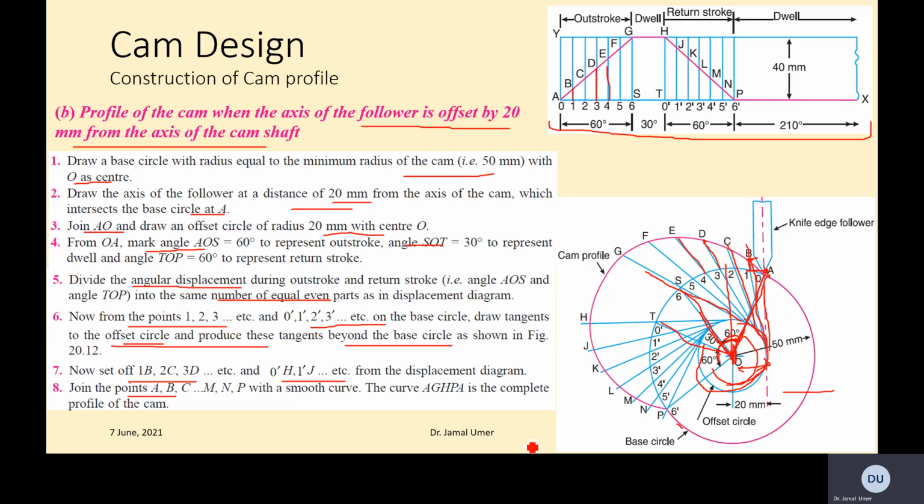Then you connect these points with a smooth curve, right? And this will give you the profile. Now you can imagine if you want a more accurate solution, because what's happening between these two lines? To get it more accurate, the accuracy can be increased by splitting into even smaller divisions. For example, instead of 6, I do it 8. This will give an even better solution because we will have a better idea of the distance between two points basically.